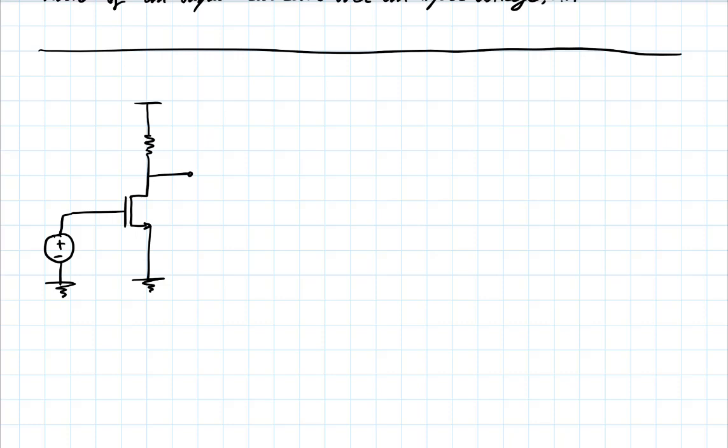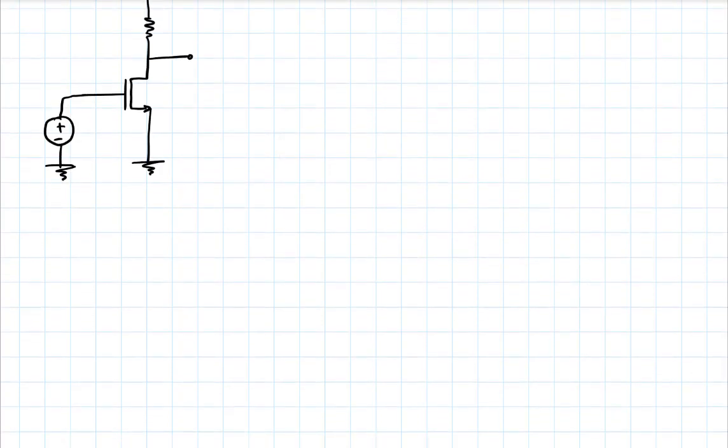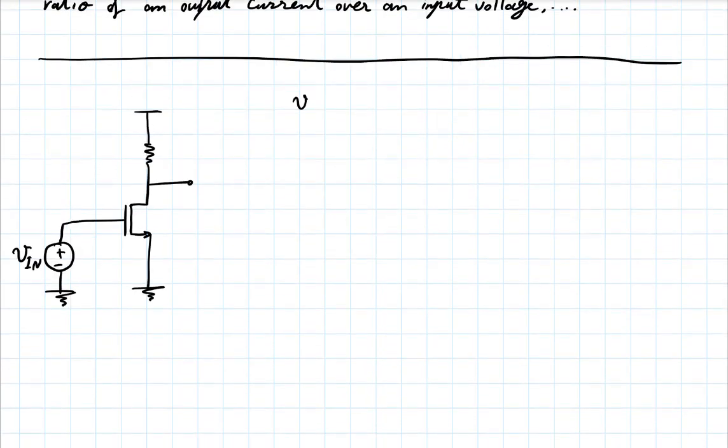Now, again, this will be a voltage that includes, so this is a V in like this, two components. It has some bias plus a small deviation from it. So let's say the big V in is 1 volt, the little V in is 5 millivolts. Okay, that's why I've written it like that.